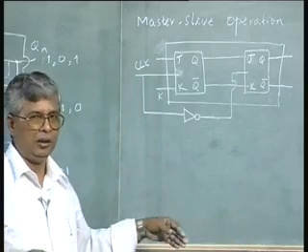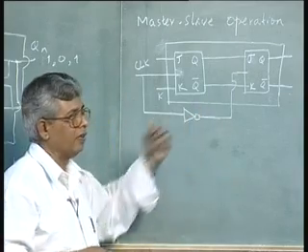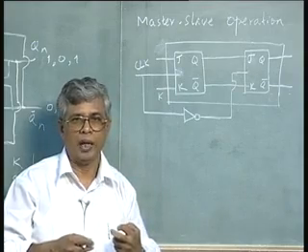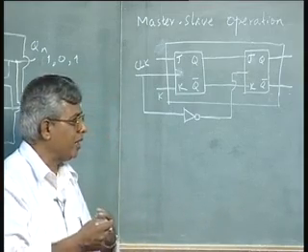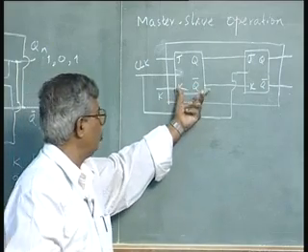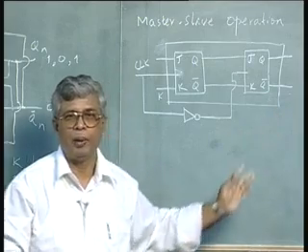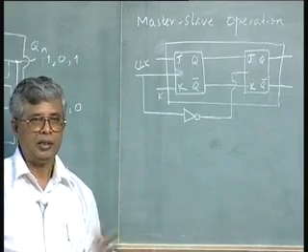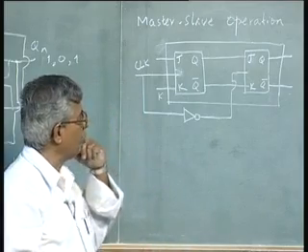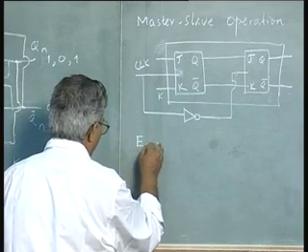Whatever it is, I don't want to question your need. Supposing you want to operate at a clock rate which is faster than the propagation delays which 2 flip flops can allow you to do, why should I be restricted in the speed of operation by having to pass through 2 flip flop hardware? Why should I unnecessarily increase the propagation delay of the path if it is not required, plus the fact that there is extra hardware required. That makes you think whether it is the best solution. Of course, as I said, the other solution is edge triggering. You are familiar with this.